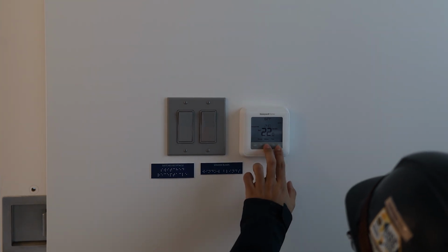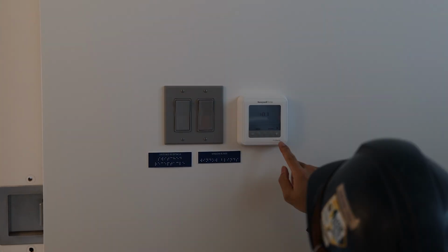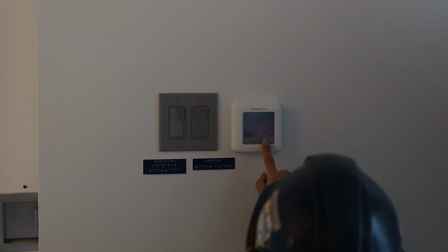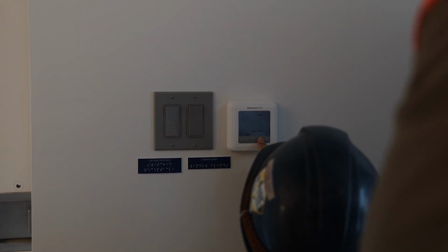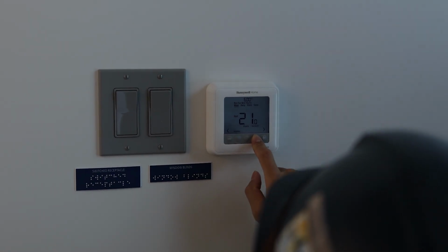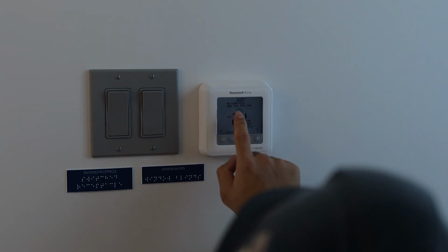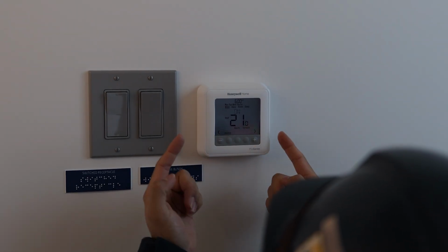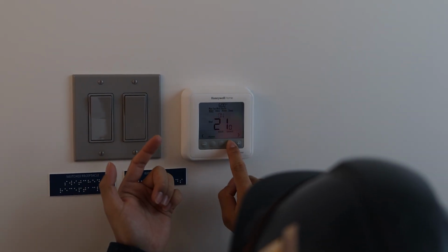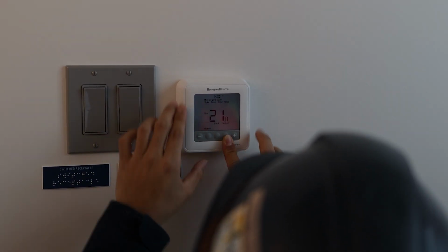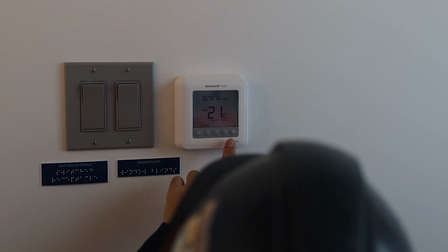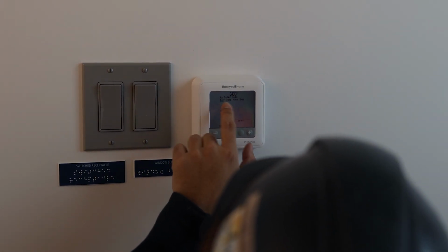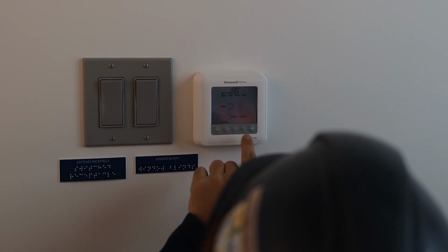So if you want to go to the program menu, hold the menu button, press plus, hold. If I go next, program. Here I press select. This one tells you this is how you program your schedule. So here it's Monday to Friday, 6 a.m. We want this temperature. We want 21 because we just wake up, right? Then we press again to change the time. At 6 a.m., we just wake up, Monday to Friday, we want 21 degrees in heating.